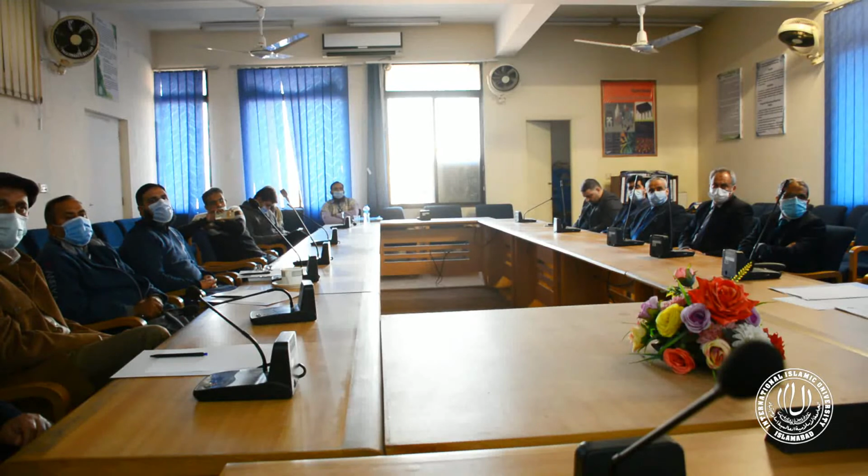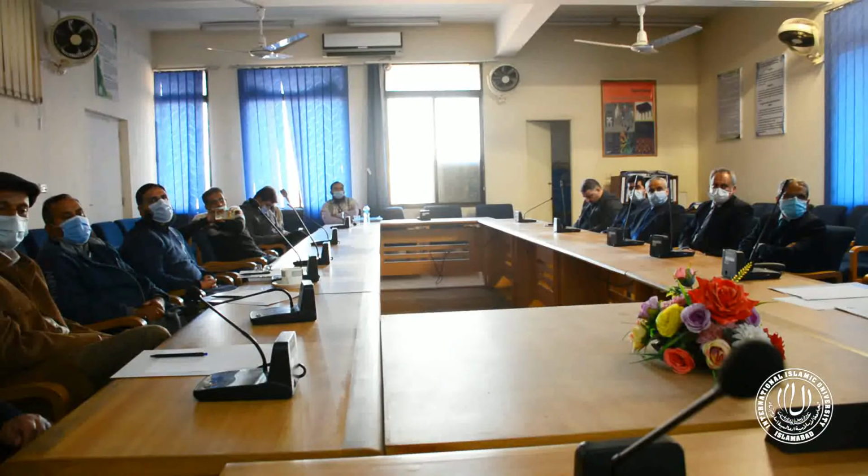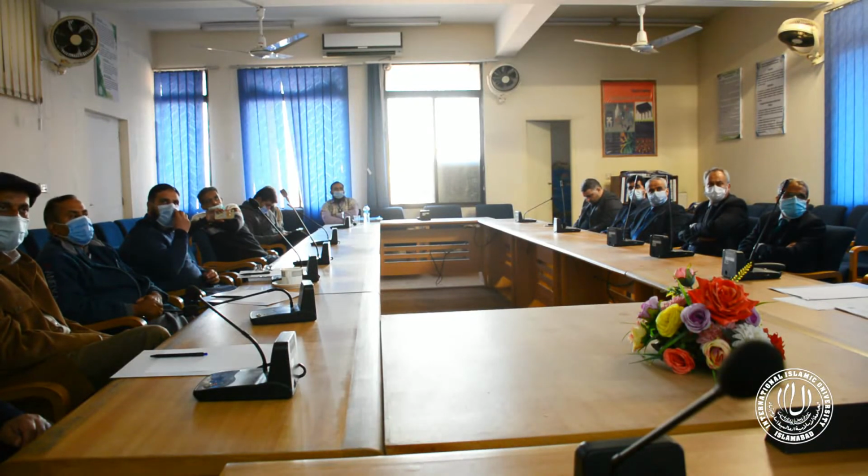So, look, during one pulse repetition interval you have active mode, which is going in the red line as shown. The higher red line represents the radar signal going. The other 4 red lines represent communications only in active mode. But in rest mode, as there is no radar, the dashed line is going to be none. But the other communications, which were already produced in the main loop in active mode, in the side loop of active mode, continue as shown here.